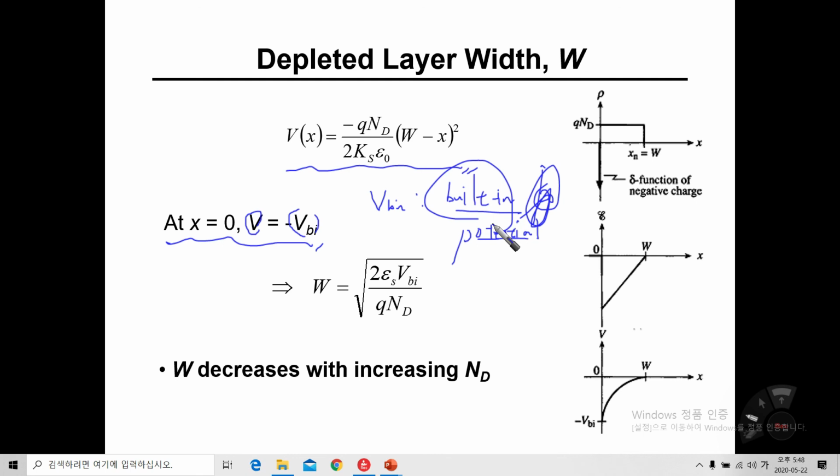So once that n-type semiconductor is combined with a metal system, resulting in the MS contact, because of the work function difference, in other words, because the Fermi energy levels of the metal system and semiconductor system are very different, the movable electrons would be swept away from the interface of the MS contact.